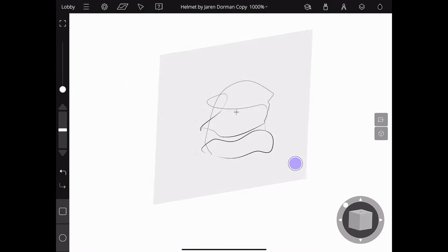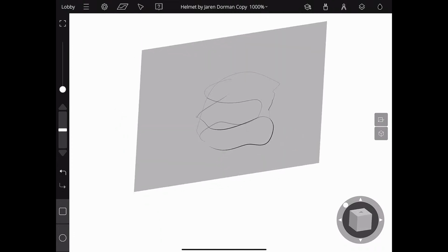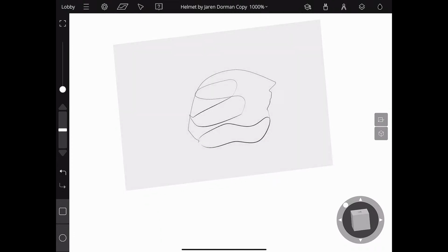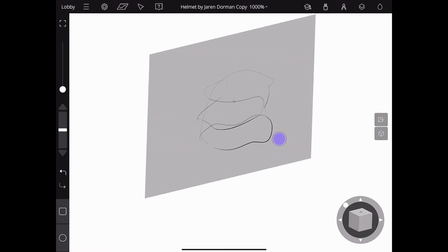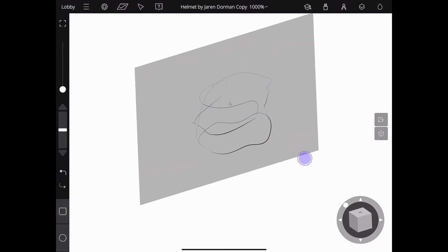So you can see now that that's how you can manipulate the curves. And so that's what I would recommend if you have something that's looping around and you can't really see what everything's doing. I would just go in the 3D view and just hold the square and manipulate your curves using that, so it's locked to that profile still and you're not losing that original profile design.